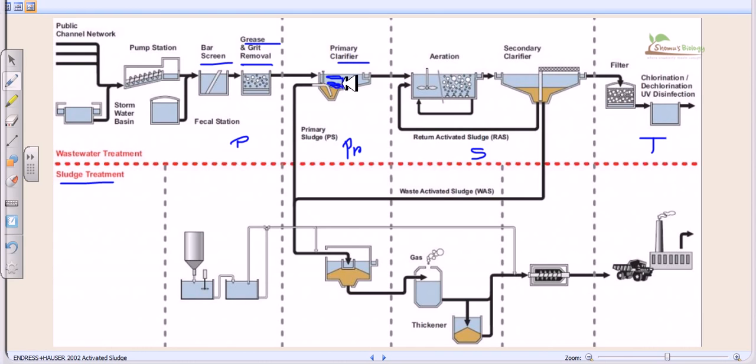And the second layer or second system which is placed here is also rotating, and this second strand is actually rotating at a very low velocity. As a result of this rotation, it helps all the small sediment, all the small particles, to settle in the lower region or reservoir tank of this primary clarifier, which is called the primary sludge. Now I am telling you this is sludge.